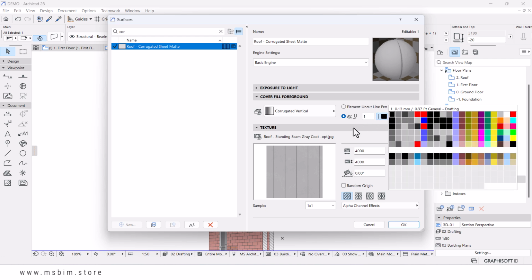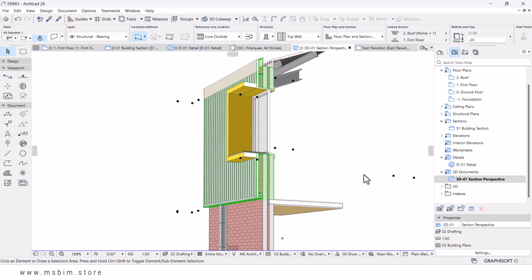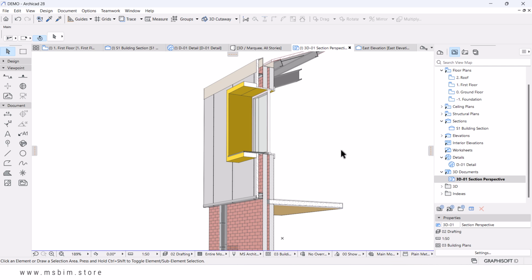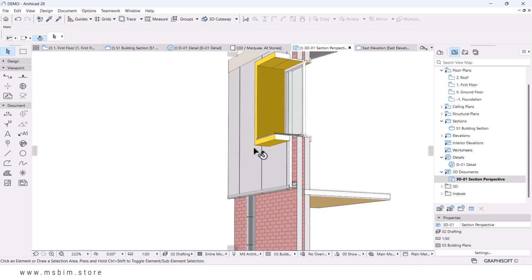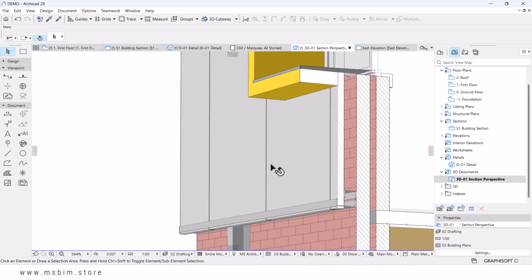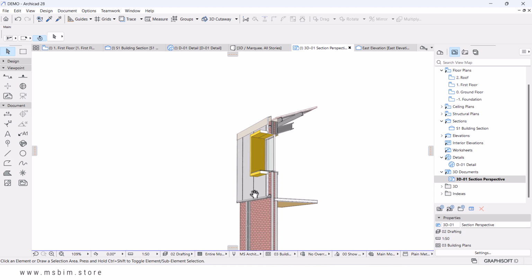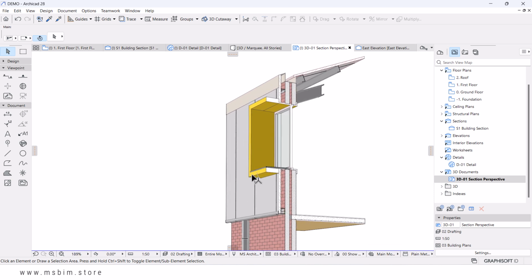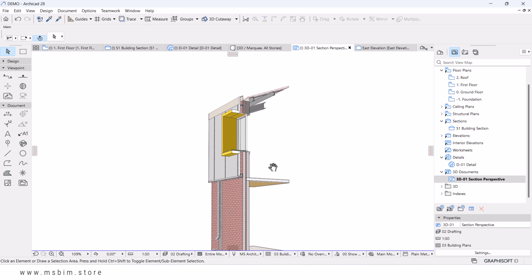Right, I'm going to leave it at 0.13, which is pen 1. Hit OK. Perfect. It's pretty much close to what I want, but I want to have it in gray color. That will represent this much because I want everything on secondary to be on a lighter weight, and then everything that is on cut to be on heavier pen weight.